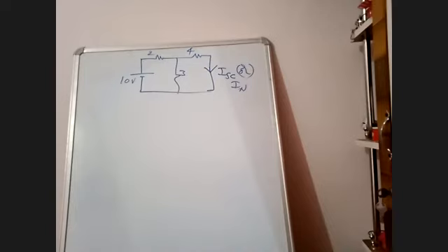In Thevenin's theorem, we have opened. In open circuit, you'll have the voltage. In short circuit, you'll have the current. Write down a note. In Norton's theorem, short circuit the resistance where they are asking to determine the current.